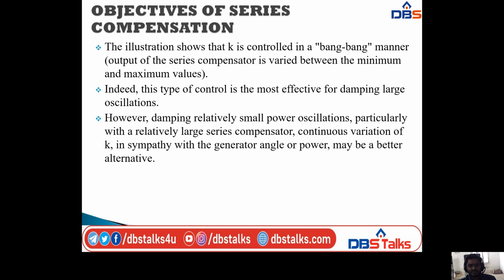The illustration shows that K is controlled in a bang-bang manner. That is, the output of the series compensator is varied between the minimum and maximum values. That is known as bang-bang control. Indeed, this type of control is the most effective for damping large oscillations.